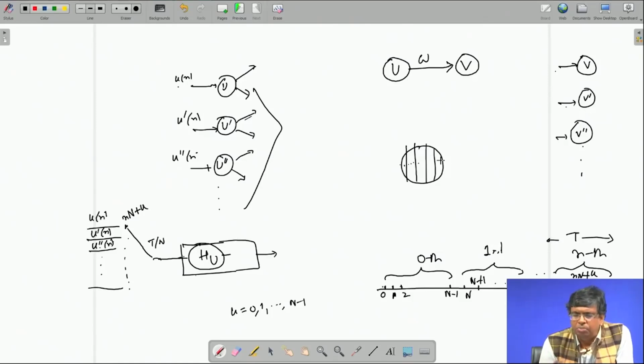Just for counting purposes, I show that number of delays separately. Here P stands for pipelining, U for the u category, and Pu is an integer, maybe 2, 3, or 4, times D. If it is 4D, then 4 delays are used to pipeline this, which means that even if an input comes, the corresponding output will be delayed by 4 cycles before it appears here.